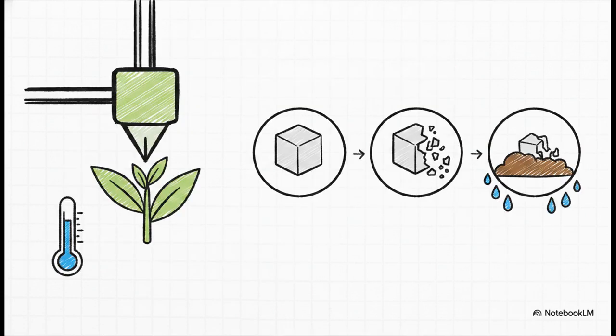Next, we've got PLA, or polylactic acid. This is everyone's eco-friendly favorite for prototyping, mostly because it's derived from renewables like cornstarch. Thanks to its flexible chains, it has a really low glass transition temperature. That means smooth melting, almost zero warping, and it's just ridiculously easy to print. Plus, those ester bonds make it completely biodegradable over time.